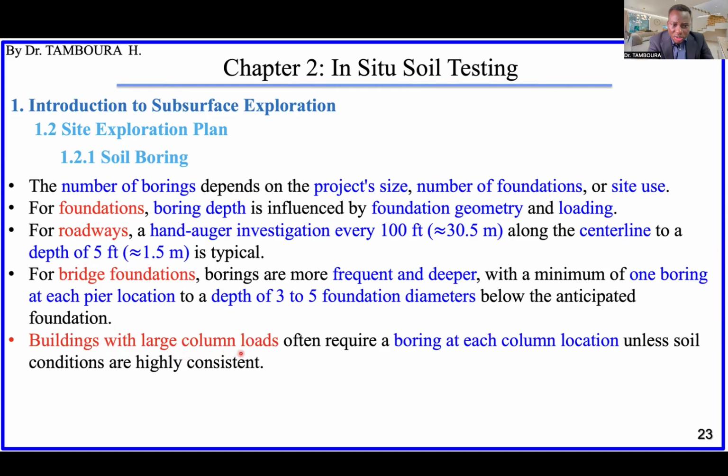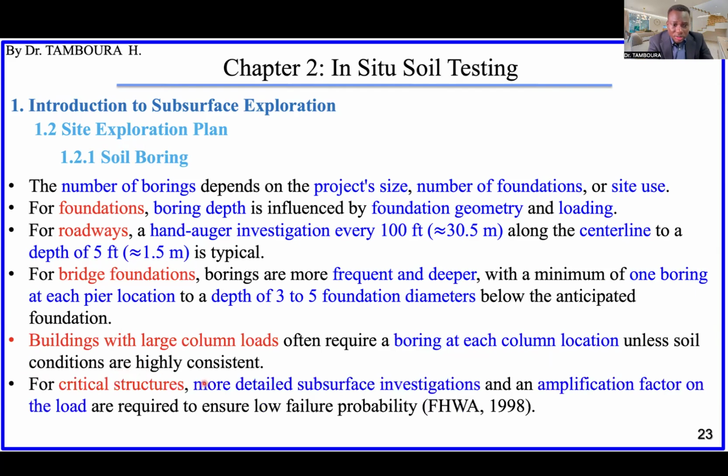Buildings with large column loads often require a boring at each column location unless soil conditions are highly consistent. For critical structures, more detailed subsurface investigation and an amplification factor on the load are required to make sure that the probability of failure is low.